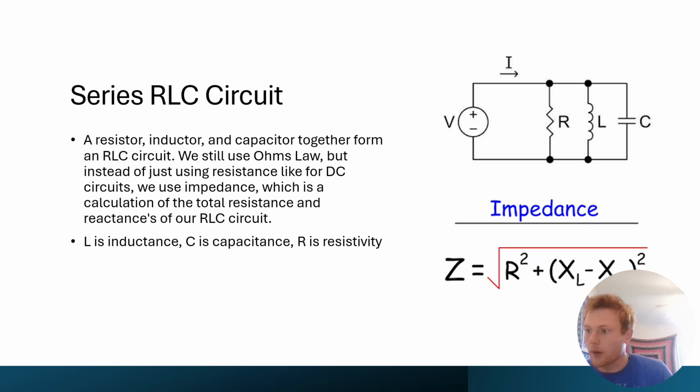All right, so we have an RLC circuit driven by an AC source. This is practice problem 11.1. Here we have resistance R, inductance L, and capacitance C, which opposes the current in a different way. The problem wanted us to find the impedance, the current amplitude, and the phase angle. My plan was to find the reactance of our inductor, the reactance of our capacitor, and our net reactance, with angular frequency being 2 pi f. And our impedance comes from that formula.